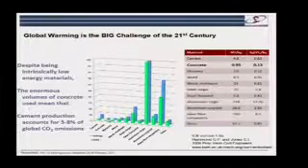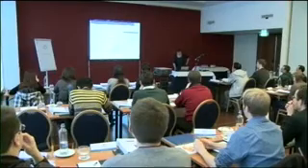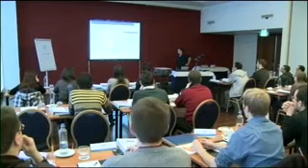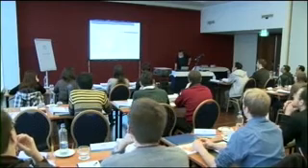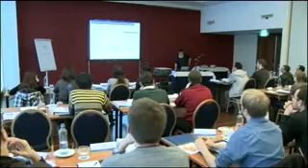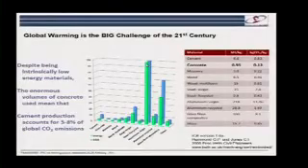Here we see a table where we compare most common materials, and on the left here I've displayed those in a relative format. These are just scaled to 100%, and you can see concrete is way down here. It actually has lower energy and CO2 emissions even than something like wood, and much, much less than things like steel and aluminium. Of course, here you can see another problem, which you can see that for both steel and aluminium, you can see the very, very big difference between recycled material and virgin material.